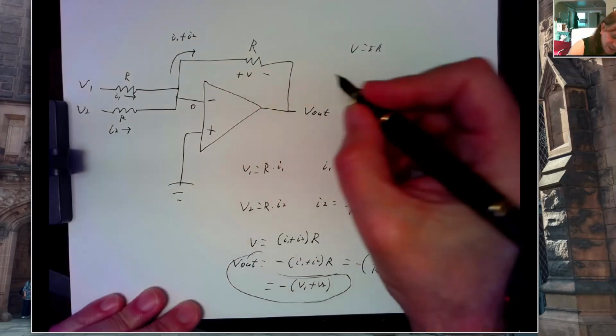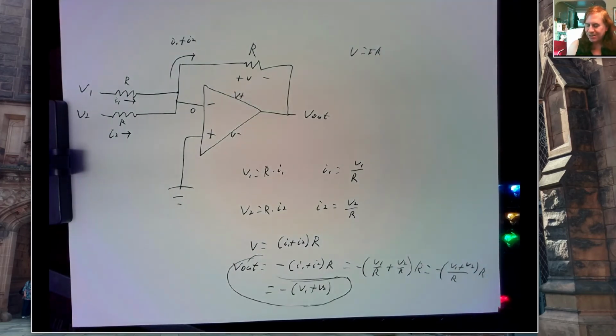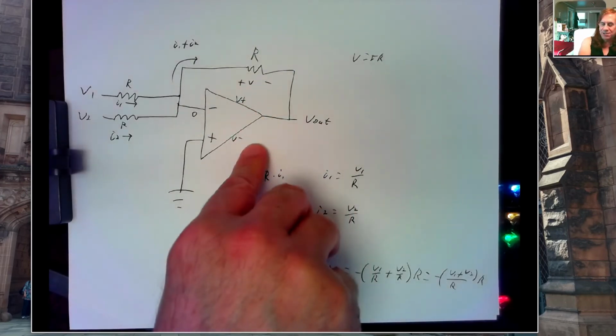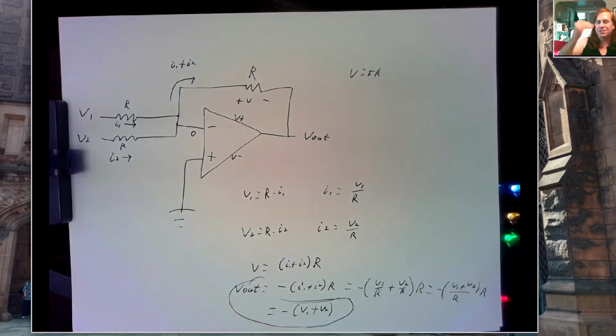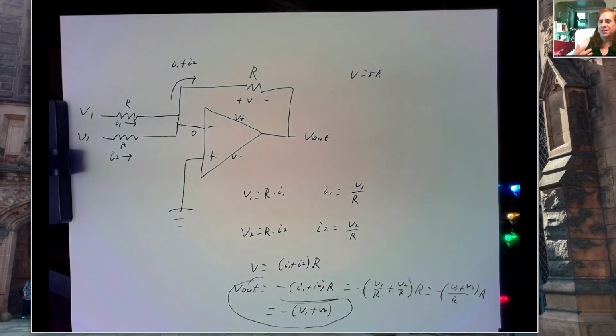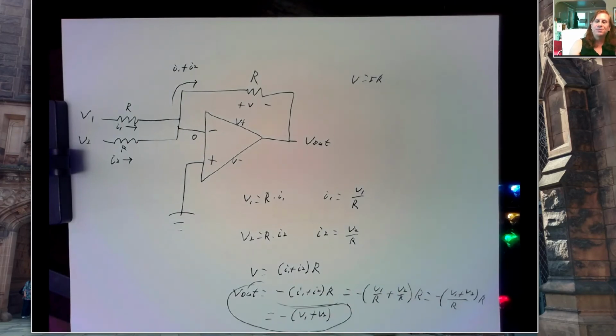If you actually connect this, there's a positive and negative voltage input. Some op-amps like a 741, you cannot get too close to these rail voltages. So if you wanted a signal that could come all the way down to 0 volts on the output, you'd need a negative voltage going into V minus. Some other op-amps like a 324 let you get very close to that negative rail without too much difficulty. But typically, we power these with something positive and negative, plus and minus 3.3, 12, whatever. And then you can work within that range of voltages as long as you don't get too close to the high or low supply voltage.